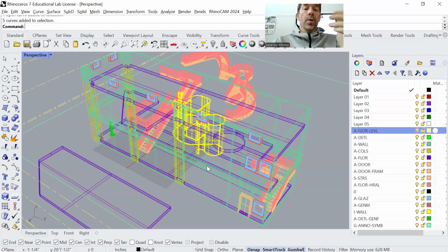For example, stairs are very easy in Revit, but as an interior designer, you might want something slightly different, picky, unique in your stair, and you're going to hit the wall with Revit. But maybe you do a stair with the basic landing in Revit, then take only the stair to Rhino and add your railing. There are ways you should be able to work across different platforms.